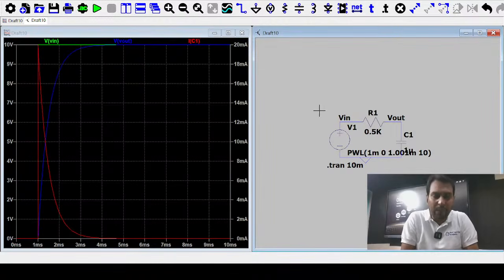So what is happening here? Basically, this happens with the help of the parasitic resistor and capacitor due to the layout. So how can you compromise this value, and how can you minimize this effect? You use a different metal or via or different things. So that's why you are learning this RC circuit.